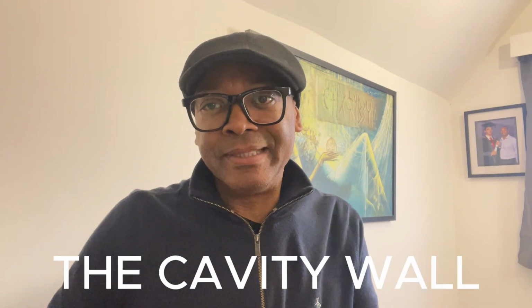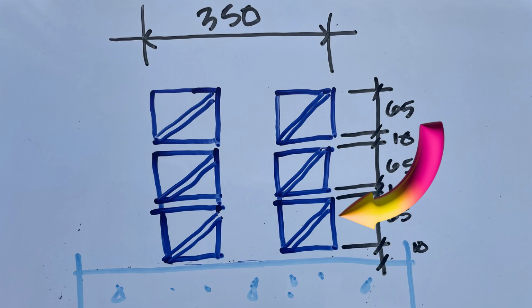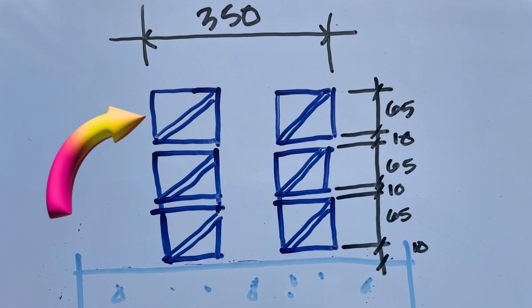So when I show you these diagrams of the brickwork, of the foundations, effectively what I'm doing is creating a slice. I'm slicing through the area that I want to depict, or at least draw and show you. That slice is called a section. So on drawings, people refer to elements of work as a section through this or section through that, but essentially what we're doing is just taking a slice through it. This element is your internal skin, and this element is your external skin.